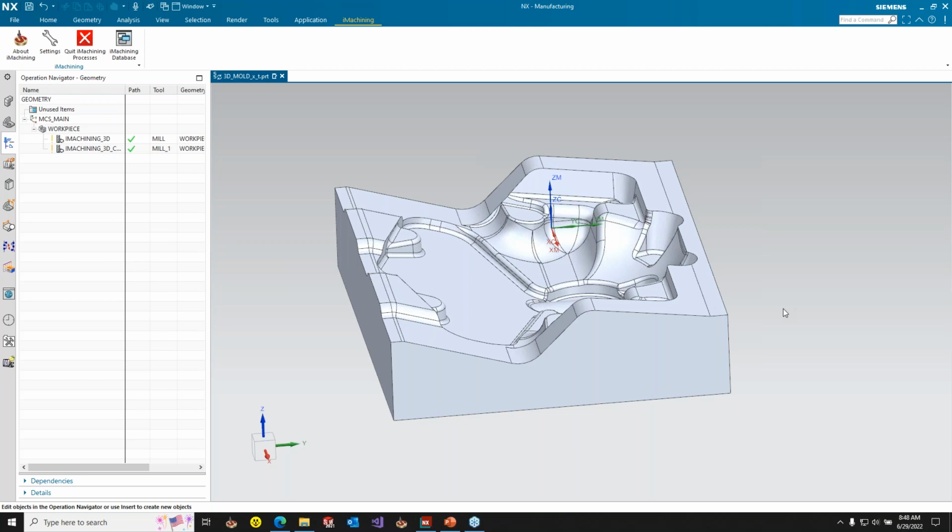But in all my experience, every time I've done conventional cutting, I can't think of a single time that I found it was something I personally would accept. But if you're doing big machining on a big part and it's aluminum and you think it's acceptable to do zigzag, climb and conventional cutting, then you can do it.